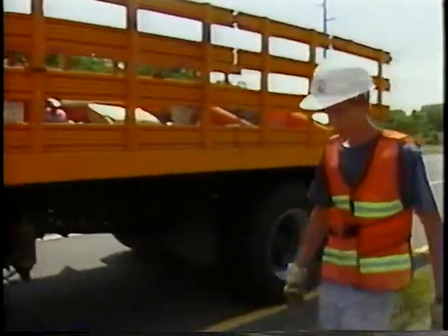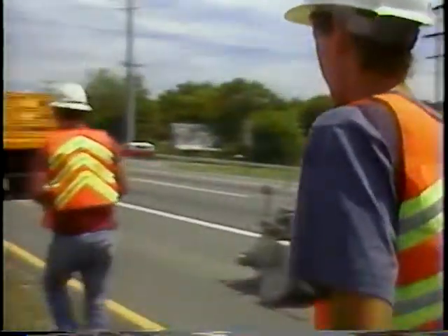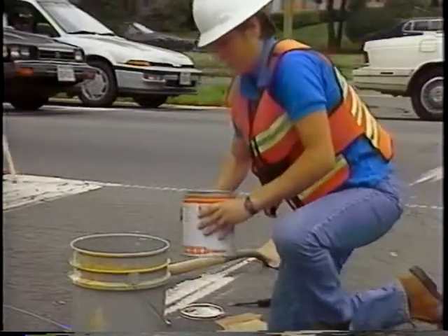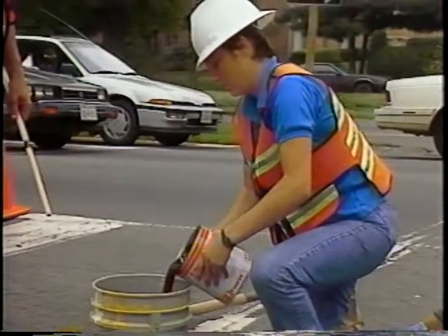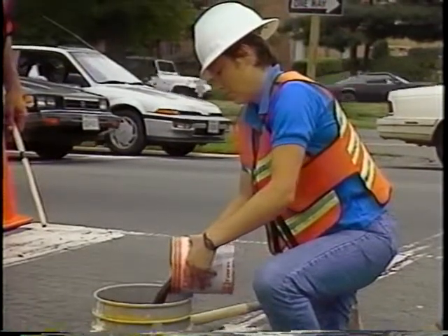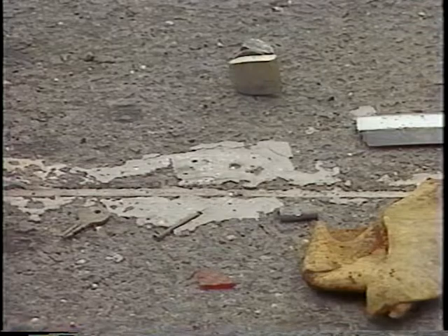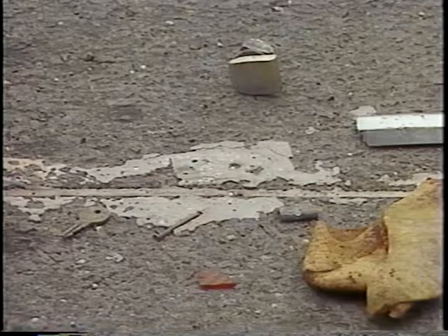The next step in loop detector installation is sealing the saw cut to protect the wires from breakage and moisture. It is important to match the proper sealant and the sealing technique to the type and condition of the roadway at your site. The sealant should be hard enough to prevent wire damage from street debris and flexible enough to prevent cracking due to pavement shifts. Also, the sealant has to withstand corrosion by road salts, gasoline, and engine fluids.